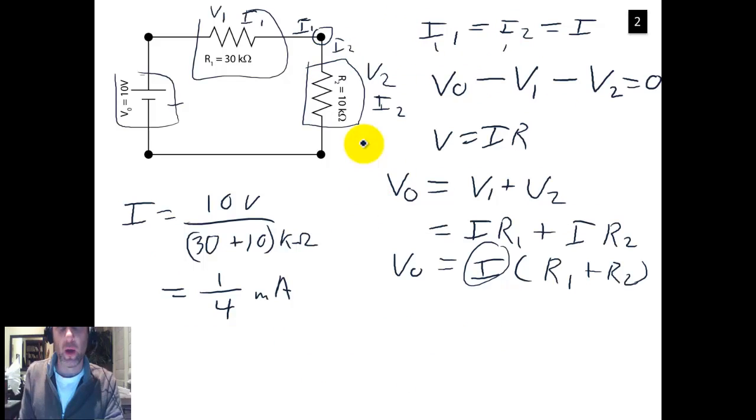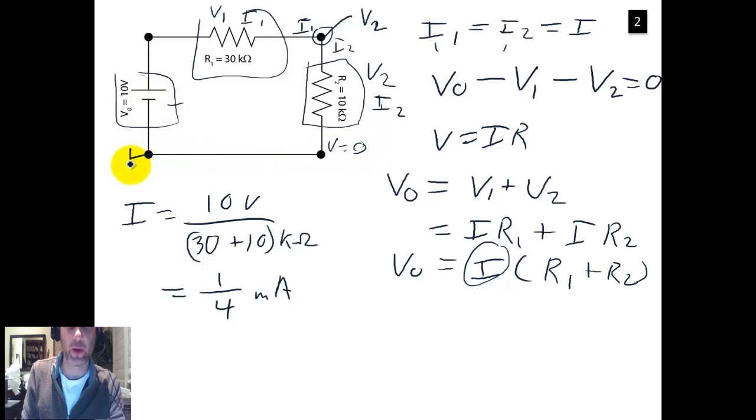do that. So let's say that we wanted to know what the voltage is there. Let's just call that V1. Oh no, we've already called that V1. It's really the voltage drop over V2. So let's call that V2, because here we know the voltage equals 0, because essentially whenever we draw that, we assume that there's a ground there. So V2 has got to equal the voltage right here.